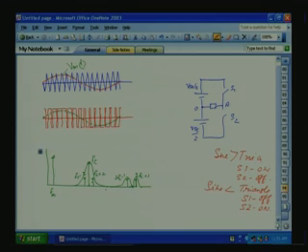If the high amplitude harmonics can be shifted to the high frequency side as much as possible, the filter size can be reduced. A filter will be an LC filter, and the inductance value can be reduced and the copper size can be reduced, so there will be a saving.